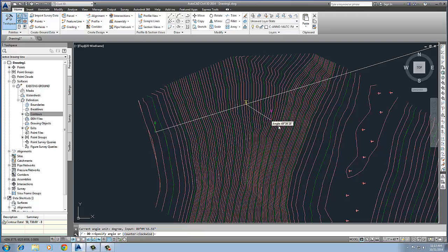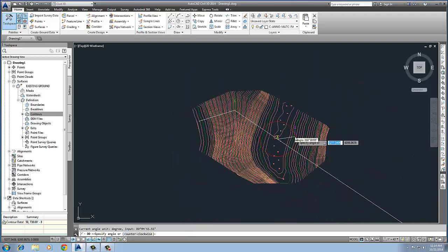So now we're going to be turning our angle clockwise. That's a positive deflection, 50.5605, and my distance is 1096.72. And notice it does increment me up, puts my instrument at my new endpoint's position, and it backsights where my instrument was, which is exactly what I want. So I'm going to turn my next deflection.